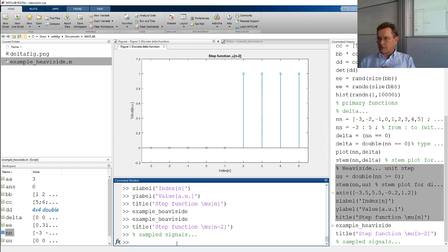All right. So in a high power processor like that one, sampling rate is set by, there are basically two ways of doing it. You set up the A to D converter. If the circuit has an A to D converter, these peripherals are usually designed so that they can give an interrupt when the conversion is done at a certain rate, since they are designed for this kind of application. So let's start.